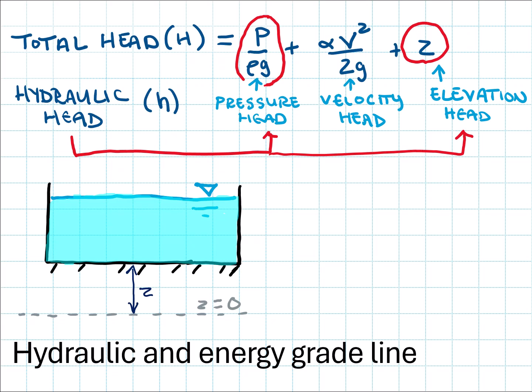So of course, I know that the fluid flowing in my channel has to be in liquid phase in order to have the free surface developing here, that interface between a gas and a liquid. And I know that the gauge pressure right here at that free surface has got to be 0. How do I know this? Well, because the absolute pressure is atmospheric, so that's going to be 0 gauge.